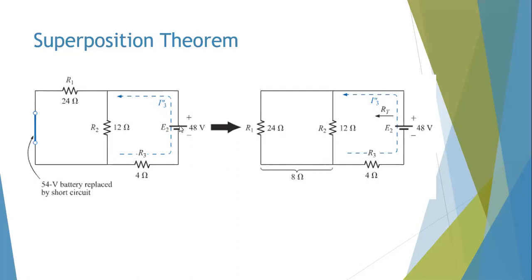So again, if you analyze how the current behaves, the current starts off here and then goes here, and then you can see this resistor and this resistor share this node. This one has been short-circuited, the source, so you can just forget about this part now. So this one is short-circuit, 0 ohm here. And the other node of your resistor is sharing the same node. So these two resistors are in parallel.